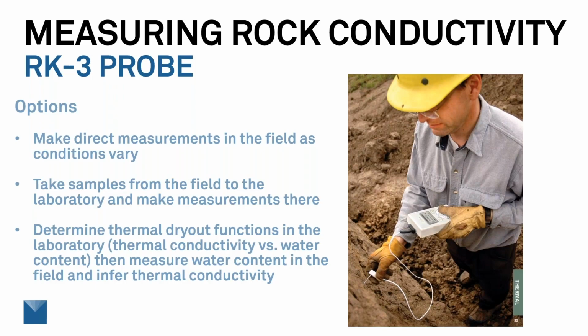The soil thermal conductivity can be measured in the field, as I'm showing in the picture on the right. In this picture, our older KD2 Pro was used. The TR3 needle or TR1 needle is the one that you would use for making this measurement. It's 10 centimeters long. You just poke that into the soil and take a reading. It takes about a minute to get a thermal conductivity measurement with this.